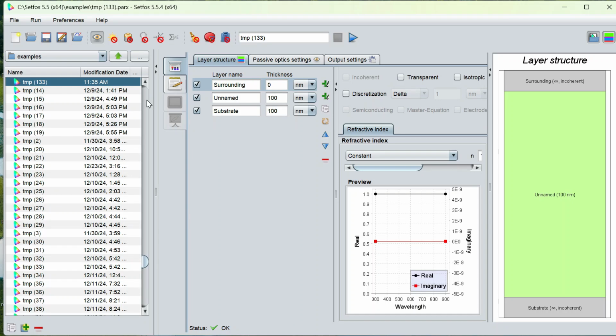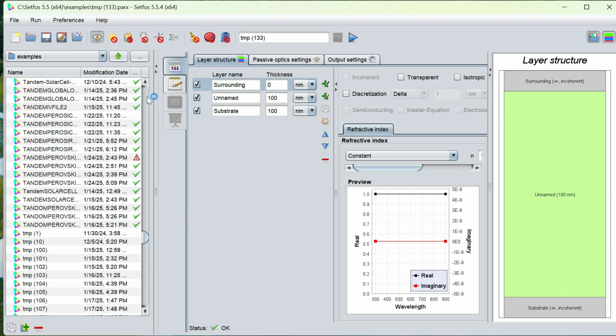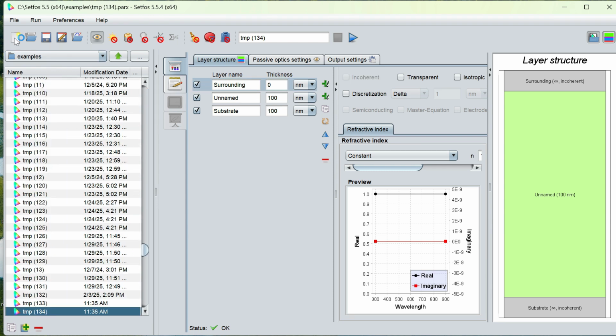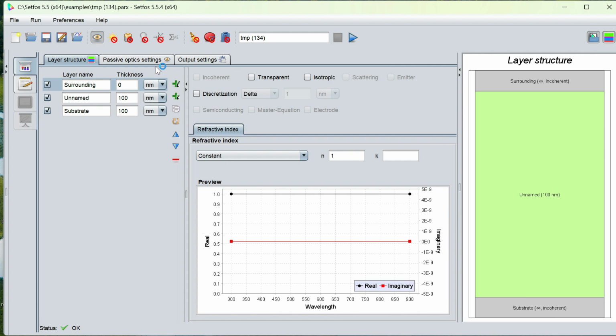Now I am going to create a solar cell application tutorial file. To create a new simulation file, you can click here. For a better view, you can click here. Basically, CT state exciton dynamics generally means that otherwise it is only possible to calculate the maximum achievable photocurrent. Here, connecting optical calculation with a charge transfer exciton dissociation and drift diffusion model makes it possible to take additional loss mechanisms into account. Accounting for exciton dynamics in organic solar cells makes it possible to reproduce current measured by the research group without assuming recombination efficiency below 1%.